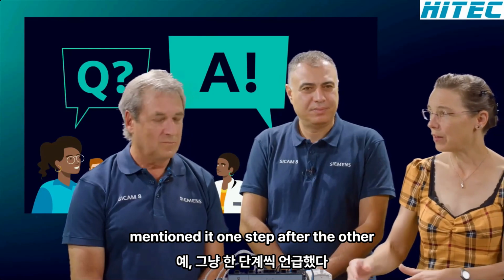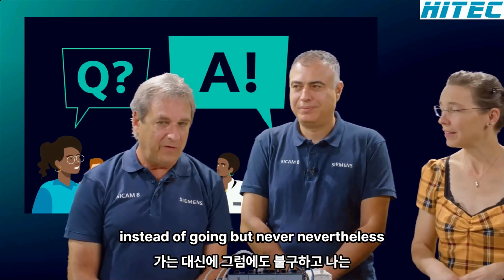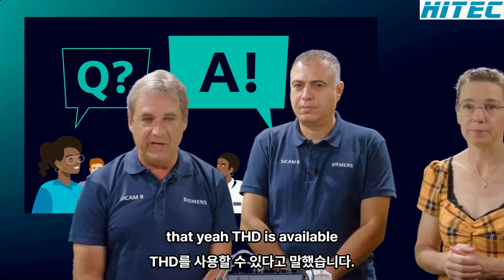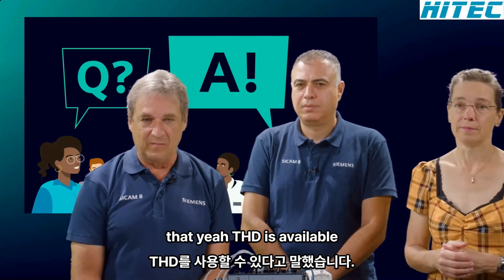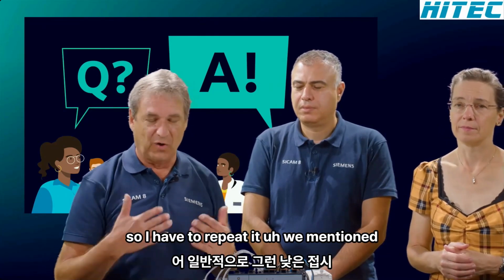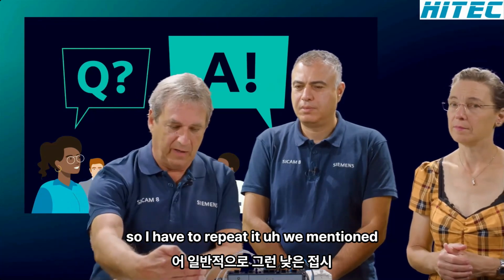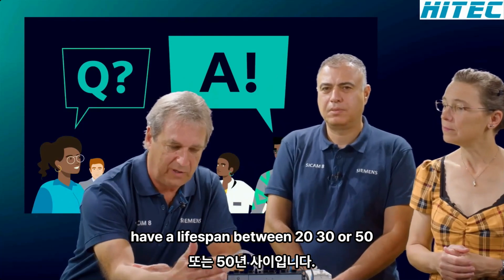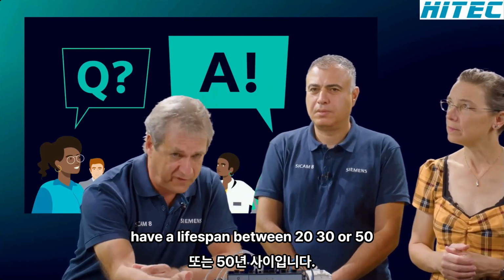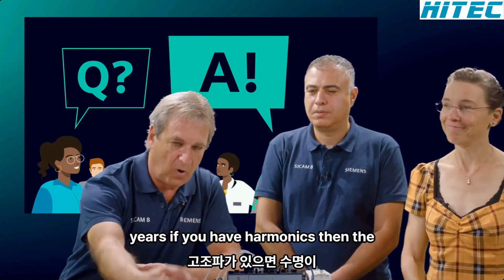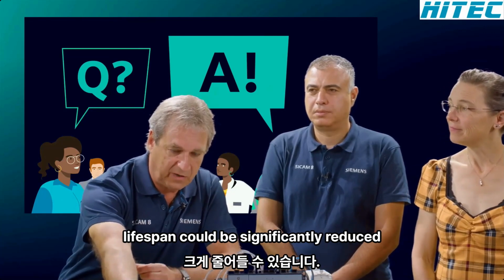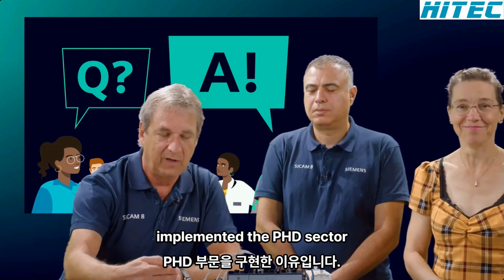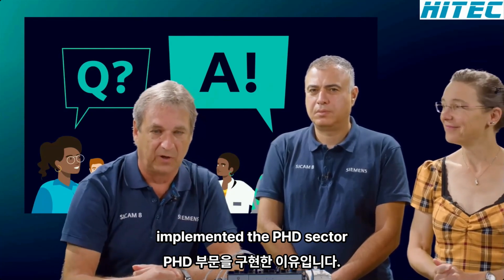One step after the other. But nevertheless, for the harmonics, THD is available. And why is it so important? Sorry, I have to repeat it. We mentioned it. Normally, such low voltage transformers have a lifespan between 20, 30, or 50 years. If you have harmonics, then the lifespan could be significantly reduced. That's the reason why we have implemented the THD factor.